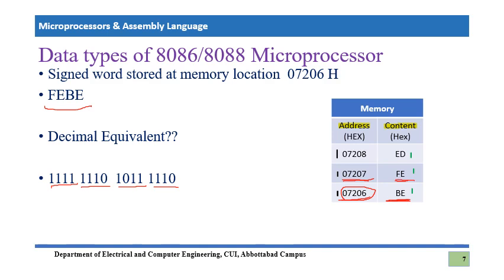No, it is a signed number, and this last bit, remember, this bit is just to indicate whether it is positive or negative, and 1 indicates it will be a negative sign. So a minus sign will come up here, and to make this complete number negative, we need to use the 2's complement. I hope you remember the number systems and their interconversion.